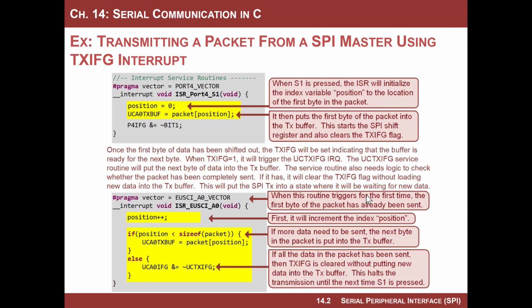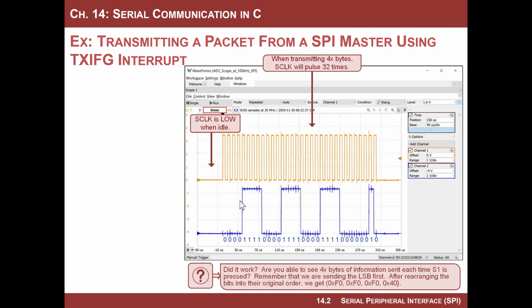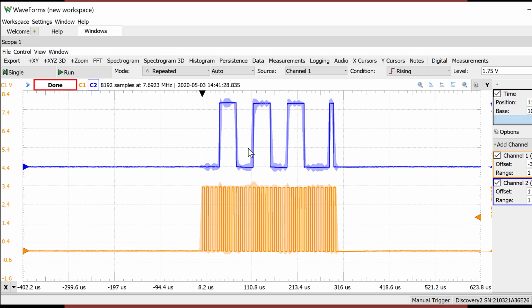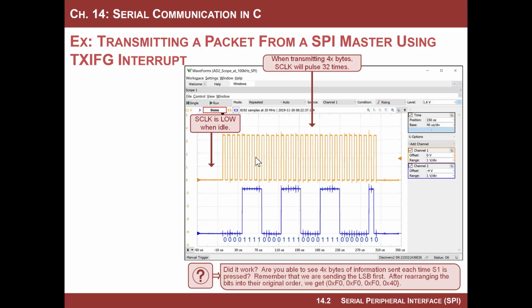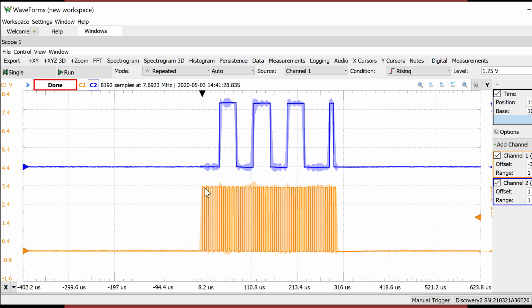So let me go to the screenshot that I took and annotated. So this is the same data, right? So here it is. I have the clock on top, but this is 32 clocks. And so if I put the little zeros and ones on there, that's what I get. But remember that they're LSB first. And so you can see that this is like 1, 2, 3, 4, 1, 2, 3, 4. So 0, 0, 0, 0, 1, 1, 1, 1.